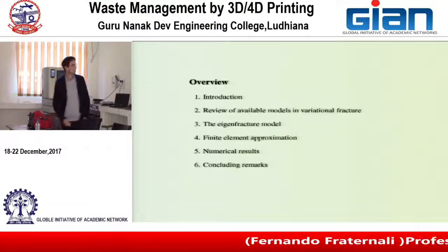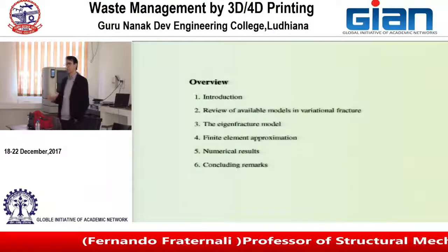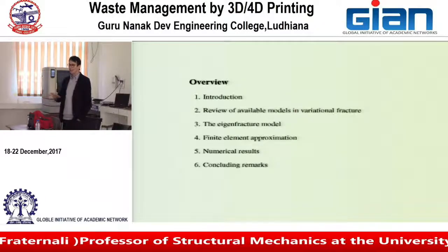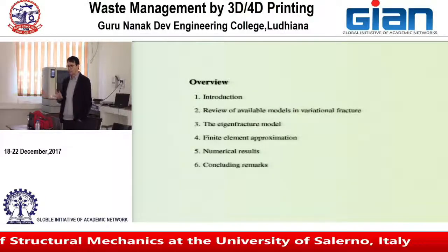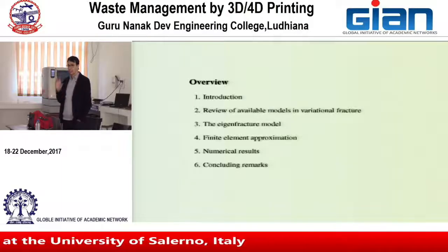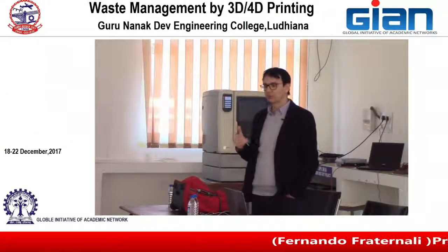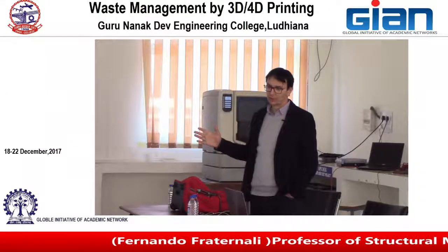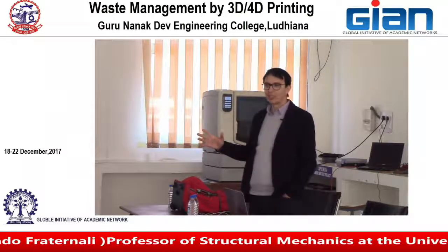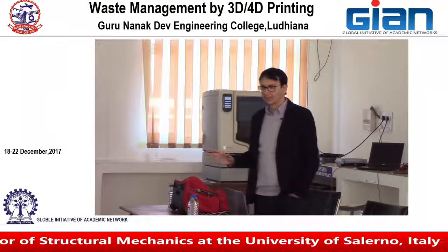So the goal is to use an energy approach to fracture propagation, to model the fracture propagation through energy minimization, without any other criteria.